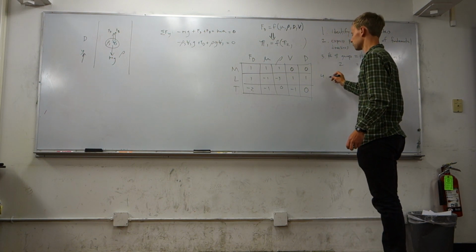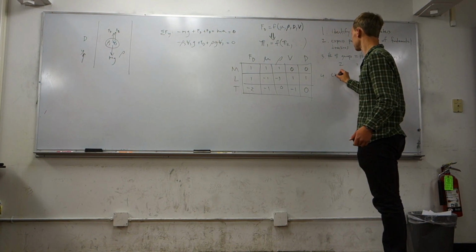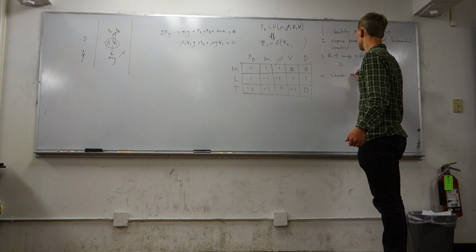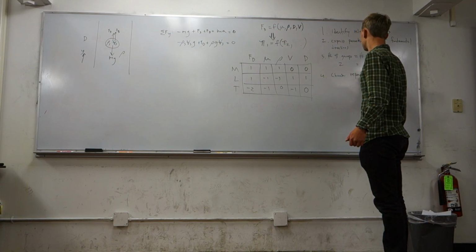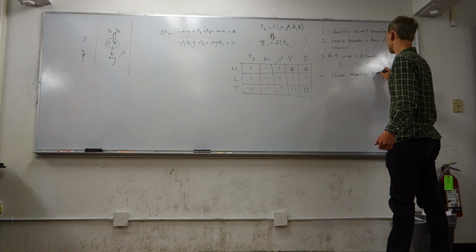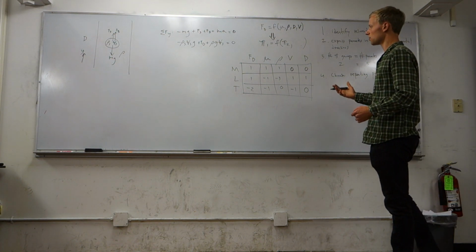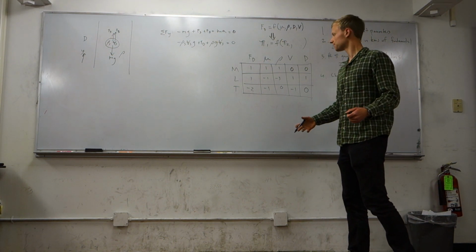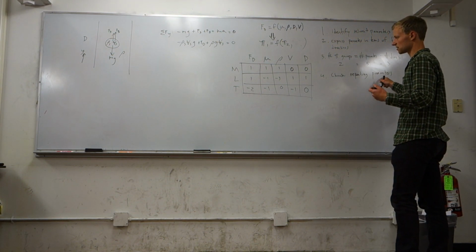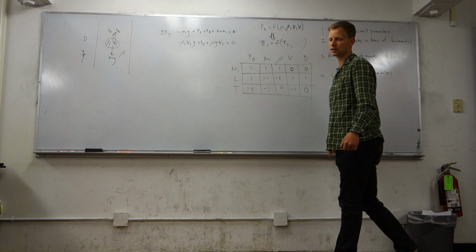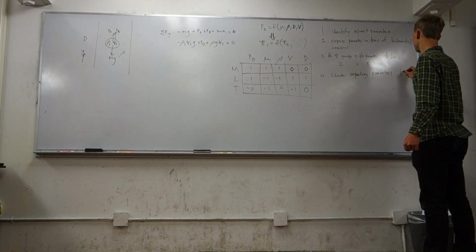So I'm going to call those things repeating parameters that we're choosing. So choose repeating parameters. And you're going to use these to non-dimensionalize every other parameter you have in your problem. And the number of repeating parameters is the same as the number of fundamental dimensions. So 3 of them.